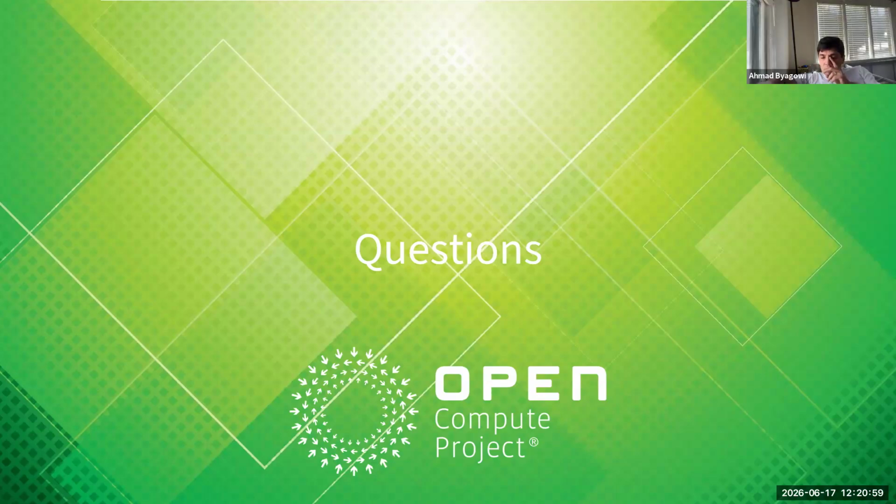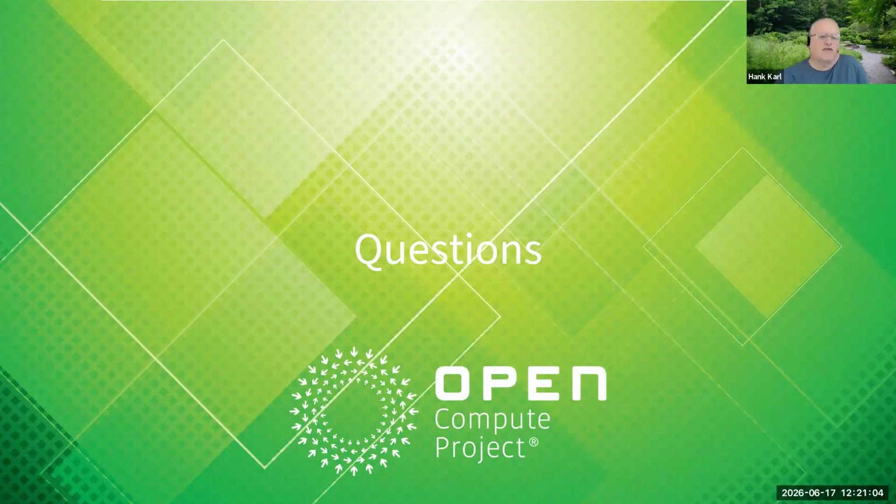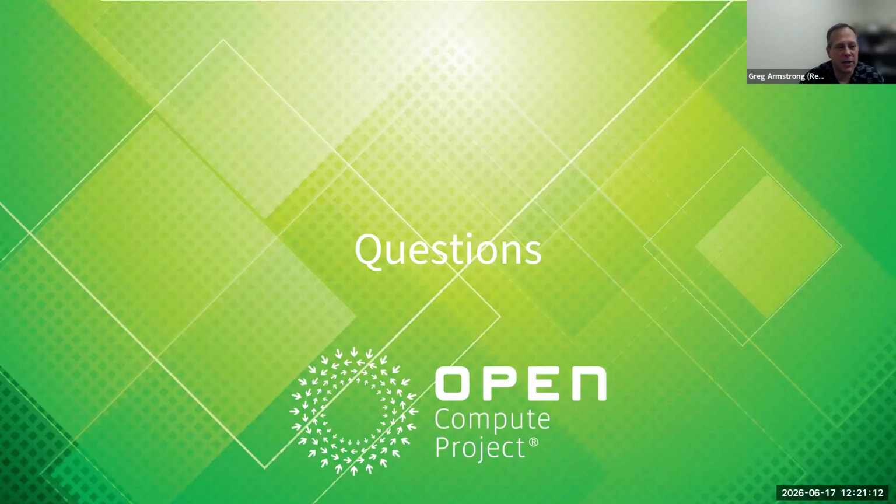All right. Any more questions? Have you considered automatically determining the delay in the cable? There's definitely ways you can measure delays of cables. I agree. There's techniques you can do. The GNSS systems are starting to do it now already. You can do things like round trip delay measurements, which means you can then compensate out delays of the cable. So I think there's techniques.